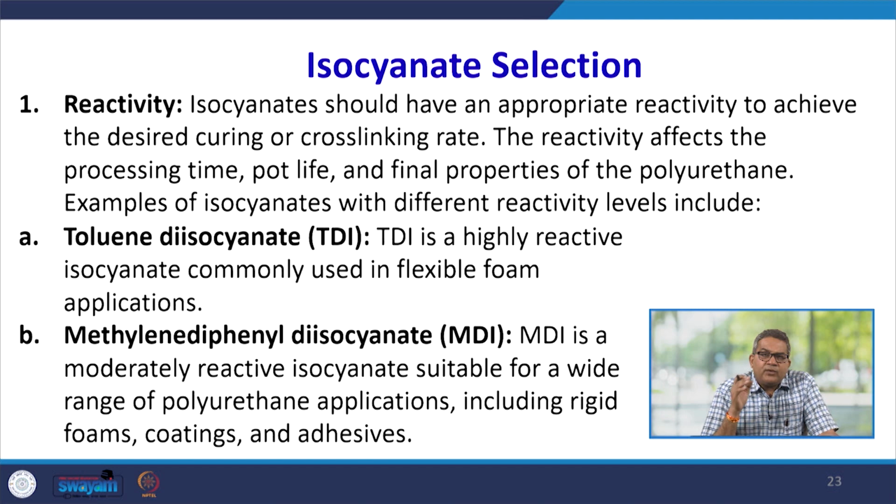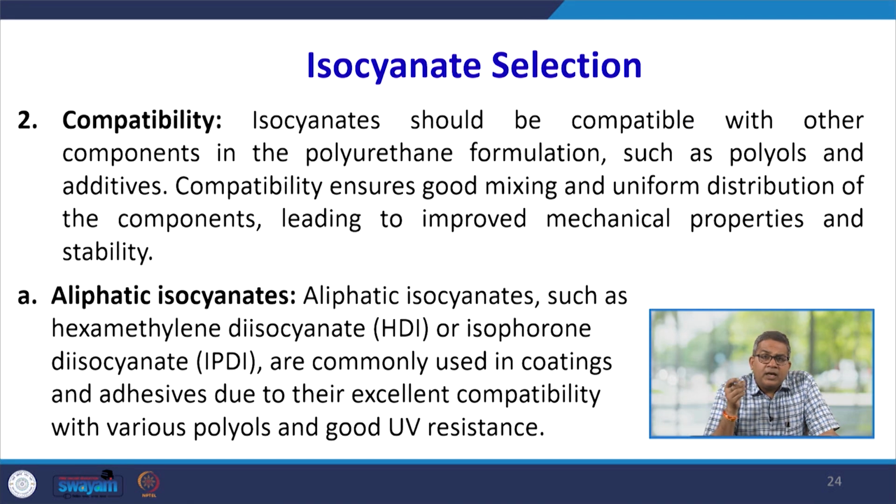Then methylene diphenyl diisocyanate, MDI. This is a moderately reactive isocyanate and suitable for a wide range of polyurethane applications, including rigid foam, coating and adhesive. Another selection criterion is compatibility.